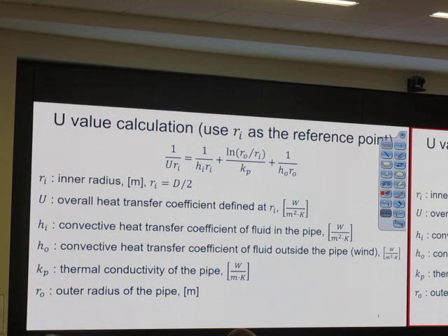Notice that if I change that K to C, everything is the same, because this U value or H value or even K depends on temperature increment. A 1 degree increment in Kelvin and a 1 degree increment in Celsius is the same increment. So if I have BTU per hour per feet square per Fahrenheit.